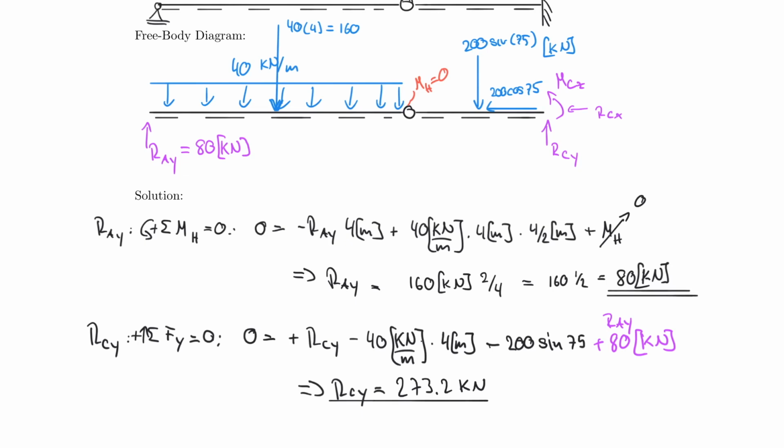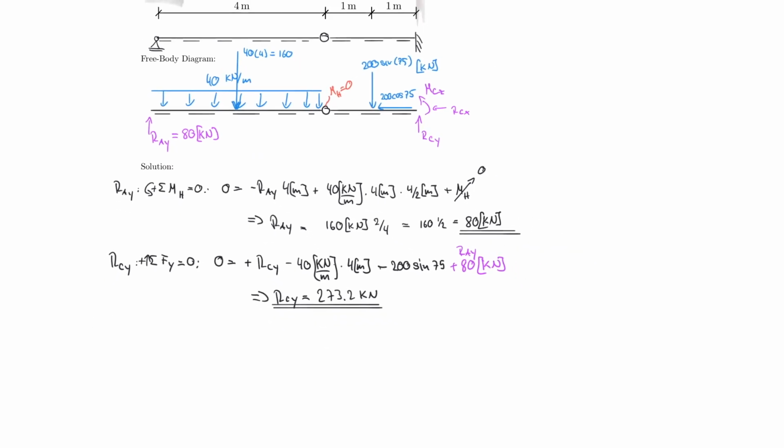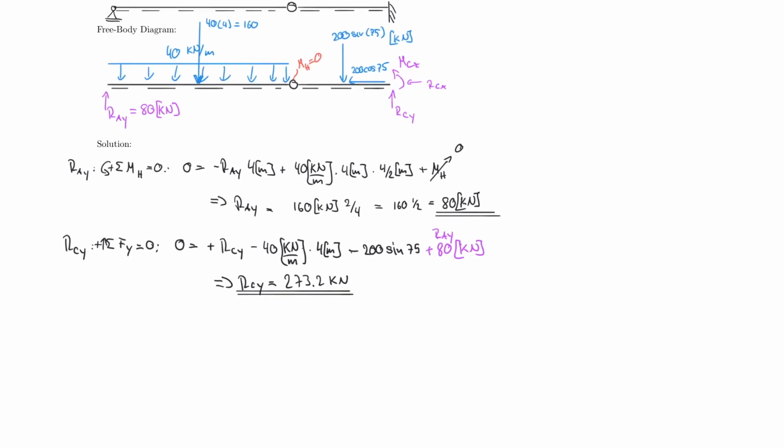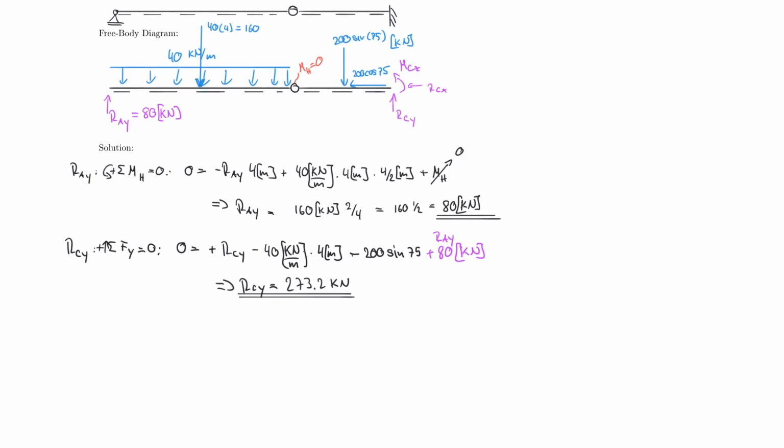So now I have my vertical support reactions, and I can continue with my next support reaction, which is the moment at the support C. What I'm looking for is MC about the z-axis, and I find that by the sum of the moments about point C, counterclockwise positive, being equal to 0. And 0 is equal to, I always start with my unknown, and notice that I assumed it to go counterclockwise. Therefore, it's plus MC about the z-axis.